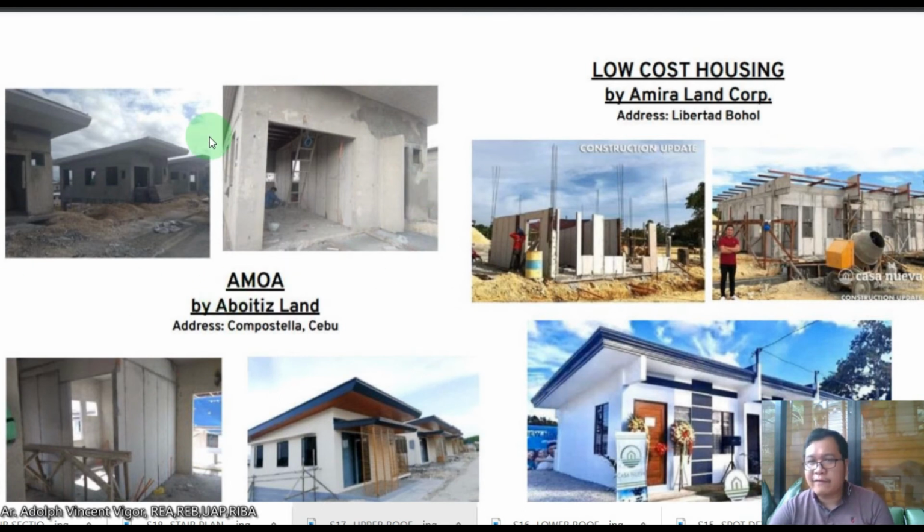Because when I arrived here in the Philippines, one of the problems that I saw was really with the construction materials, especially with CHB. So when you line up CHB, it's really hard to monitor the people that are piling it in the site. So it's hard to make it plumb. If you can't get it plumb and it has a certain deviation, then you're going to spend a lot in plastering.